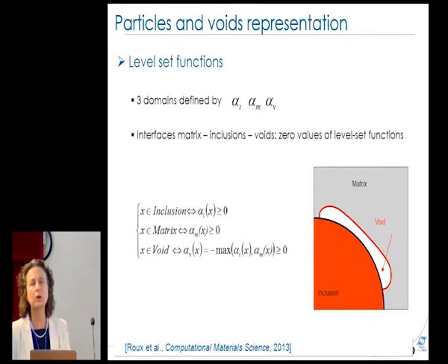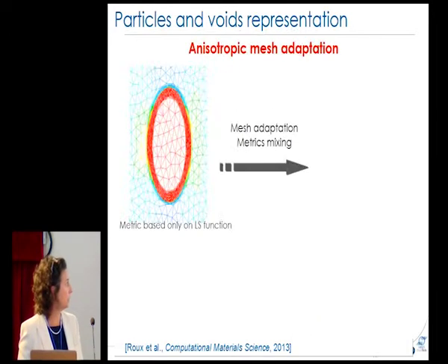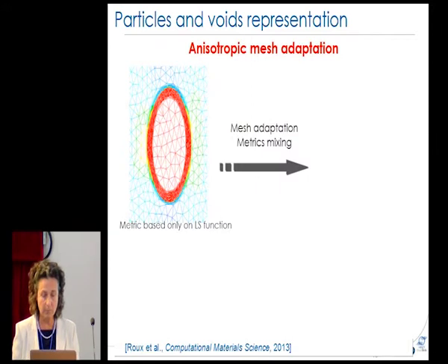Here it's a real microscope image in which we have a small particle of second phase, and we pass a mesh on this image, and we create this finite element mesh in which we apply the boundary conditions, for example thermomechanical, and we try to see if we have some problems.